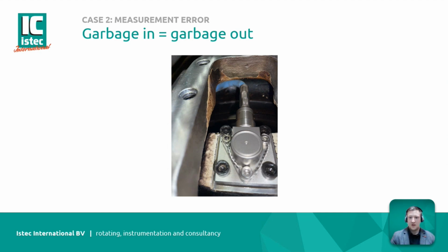So from this case, we can learn that a simple error in the mounting and routing of a sensor, because as you can see on the picture, it's not the sensor's fault, it's not the cable's fault, it's the routing. The cable is not routed properly, or the connector is too big. During the installation of the sensor, there were some mounting errors, which led to this.